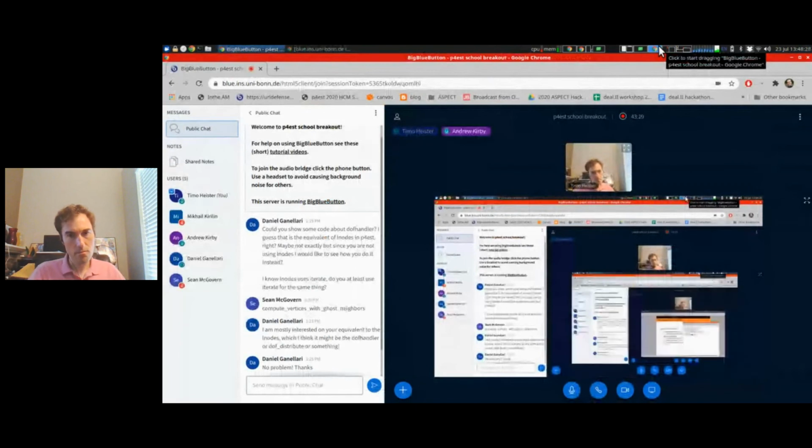Yeah, I've run into a number of issues you've already highlighted. So the 32-bit limit popped up when we were doing a wind turbine wake simulation, and I was calculating a simple L2 norm of the residual vector. And yes, I had overflowed and got a NaN. I was like, why is the simulation crashing, right? That's my one signal. And I noticed, oh, okay, we're running up to this 4 billion limit, and that's what's happening, right? So I've already started to experience a number of things just like you have.